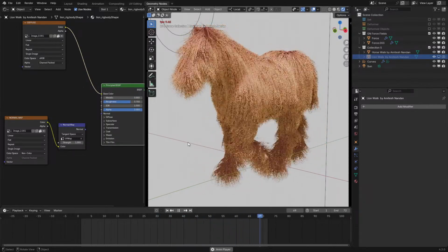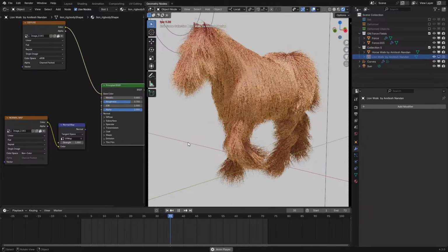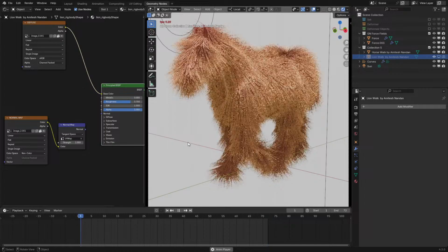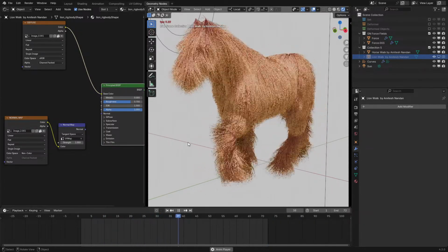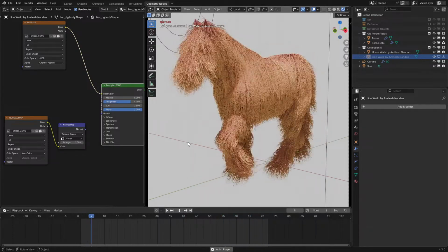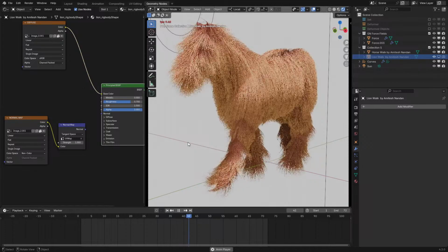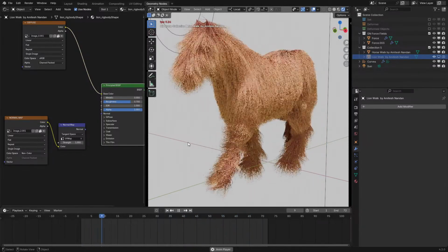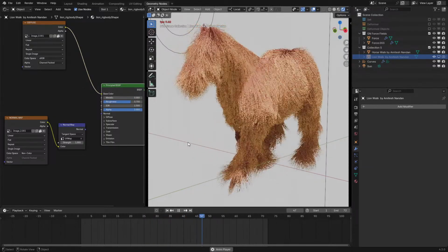Oh, with the Unreal comment, yeah, but Unreal doesn't struggle with complex scenes where Blender slows down to a crawl. Yeah, I mean, Unreal is made to be optimized in that case. It has auto-generated LODs and stuff like that, where Blender doesn't have that. With Blender, the intention is that you do the optimizing yourself. So you hide the stuff that you don't need for animating, and then when the fancy render time comes around, you do the stuff.